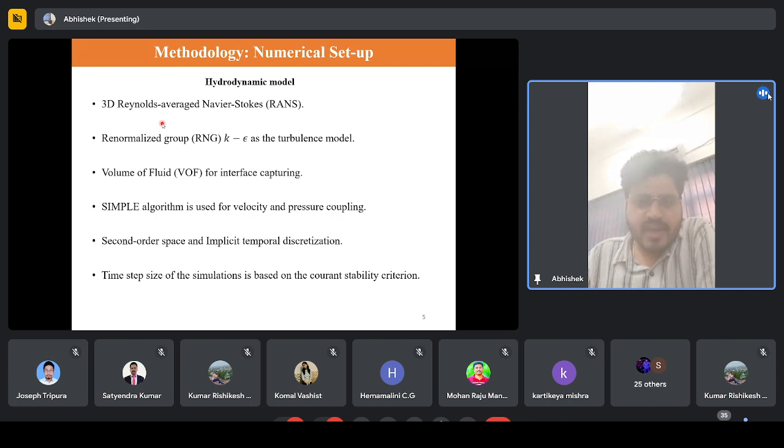concerning CFD modeling, and then you will learn what the applications and limitations of various turbulence models are. So for today's work, I have chosen the RNG k-epsilon model. It's a variant of the k-epsilon turbulence group, and the choice has been made based on a comparison that I will show you in the next slide. Again, that's a water and airflow. That's a multi-phase flow, and for that purpose, I have chosen the volume of fluid method for computing the water surface elevation in our simulation.